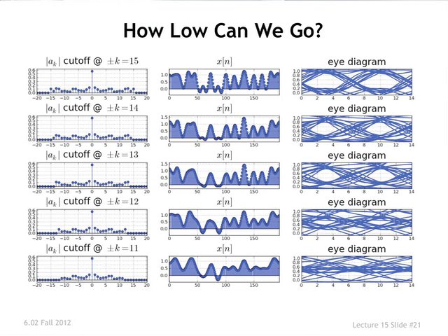And what you have coming out the other end is something that can't take the sharp turns anymore, so it's much more rounded. And as you narrow it down still further, you get even more rounding, and you get a spilling over. You see this sharply confined rectangular pulse now spills over into the adjacent slots. And you can go still further on that. The top plot here is the same as the bottom plot in the previous one, but this is just showing the sequence.